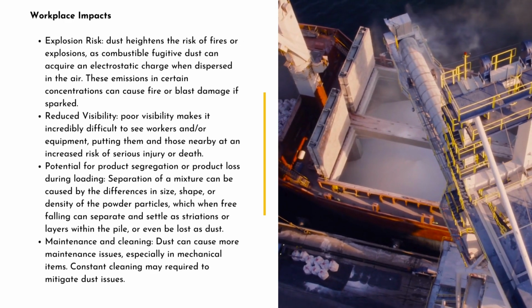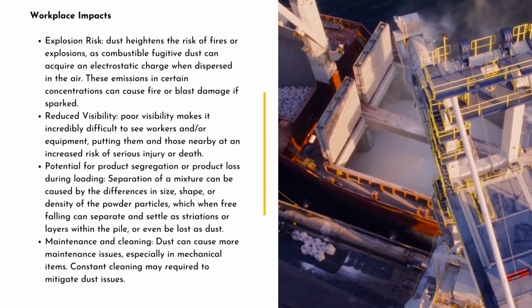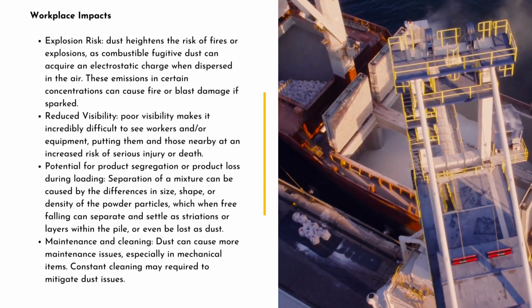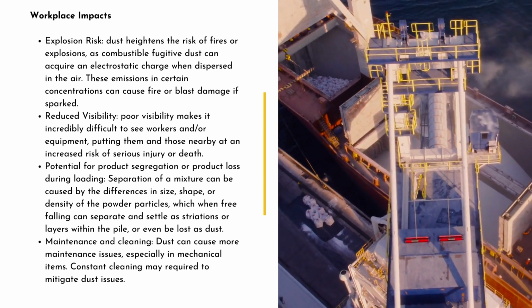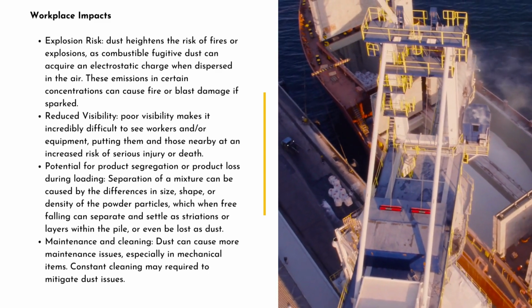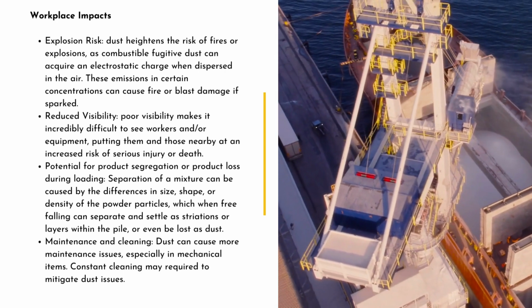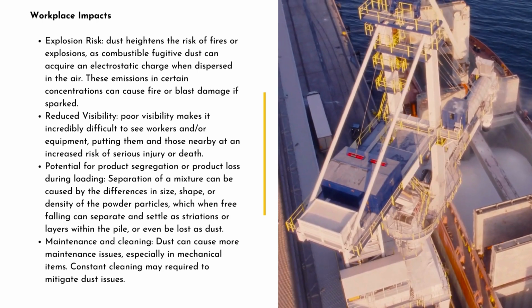Finally, dust in the workplace can have significant effects outside of what we have already mentioned. Having dust in the air can increase the risk of fires and explosions, as at certain concentrations combustible dust particles generate an electrostatic charge that can be set off with a spark from equipment, or anything like that.